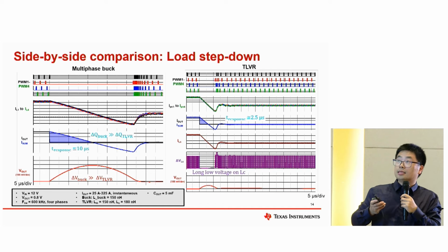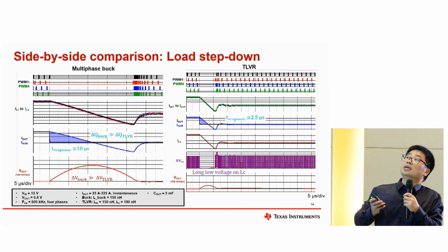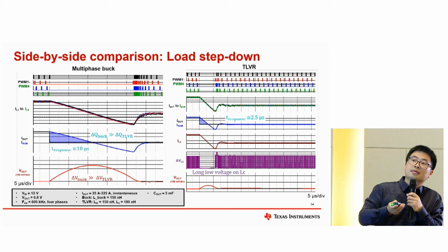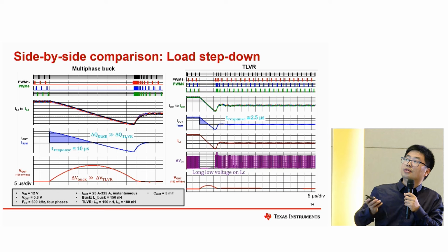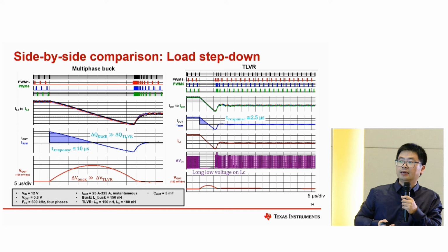And this is the simulation of the load step down. We can see that the response time for the multiphase buck is 10 microseconds, and for TLVR it is 2.5. This improved a lot. Also the overshoot for TLVR is about 1/3 or 1/4 of the multiphase buck.